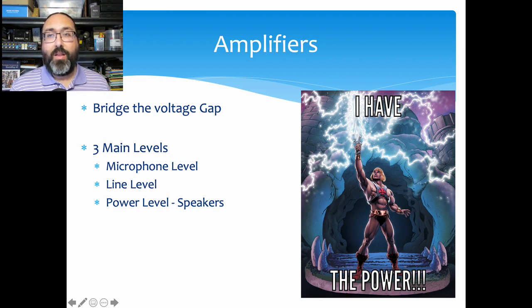Specifically, if anybody decides they want to use the turntables and mix that way, yay DJs, and do it old school, there is a specific phonograph level that runs at 0.003 volts that you need a very specific preamp to get from the phonograph to a line level signal. It's specially made. You used to be able to go to Radio Shack and grab one, but Radio Shack doesn't exist anymore. So you've got to order one online.